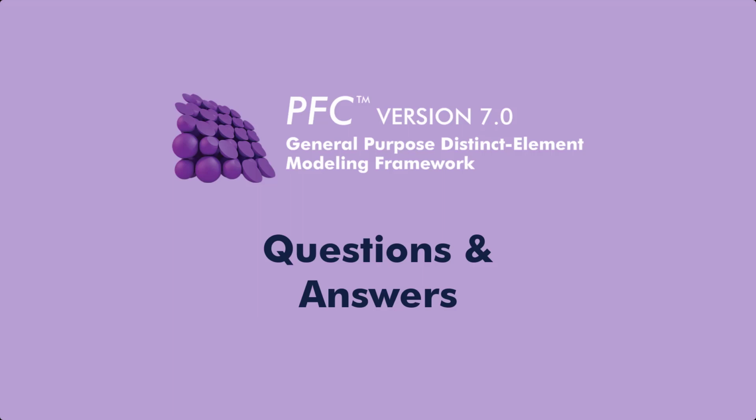Really, it's because of the use of lattice theory to compute the stiffnesses at the contacts. That's something that we don't do in the other contact models, at least effectively. And also this force correction for the Poisson's effect, which is based on continuum theory. So the spring network model for the elastic response, interestingly, is really this kind of hybrid discrete continuum model.